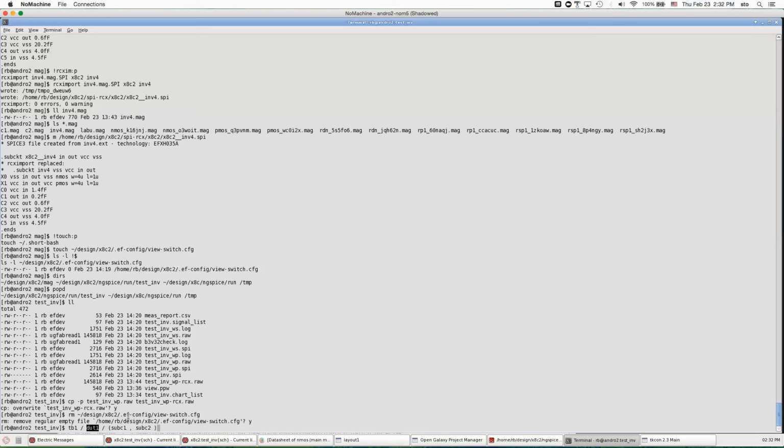If somebody really wants to see what's going on, one can look at the electric netlist after the switching has occurred, and observe how the switching is accomplished in the netlist. All these RCX netlists get included at the end of that netlist. So the native electric netlists will be earlier in the file, and all these included RCX netlists will be included after them, so they have the last chance to redefine.